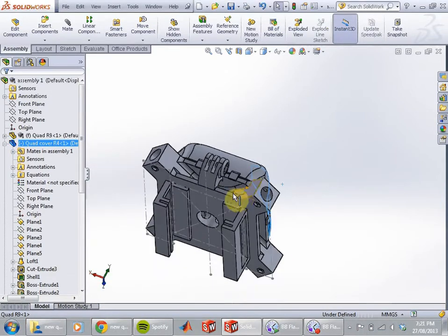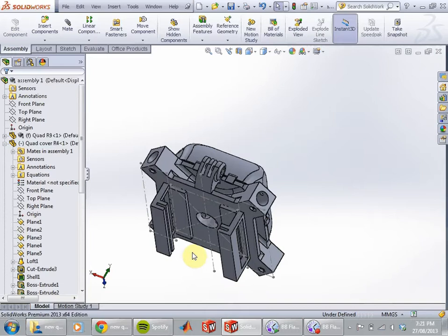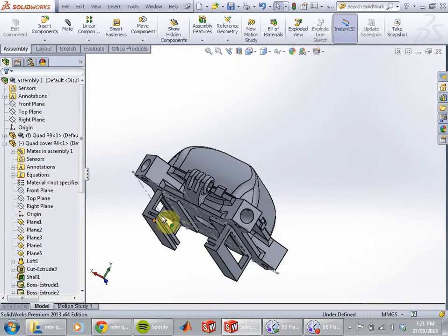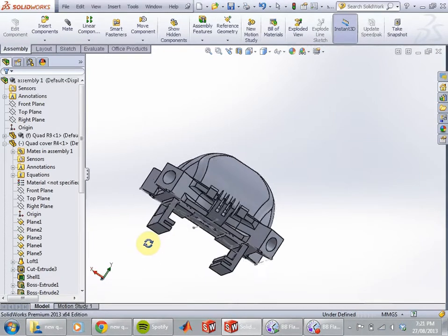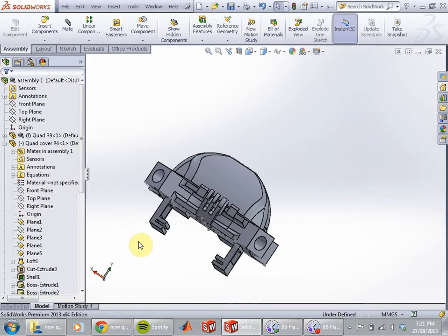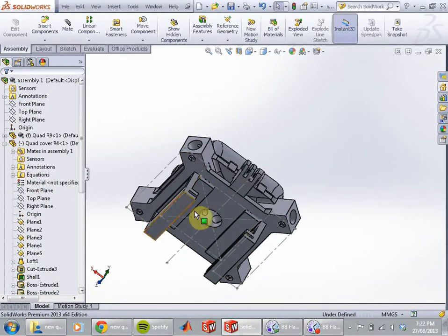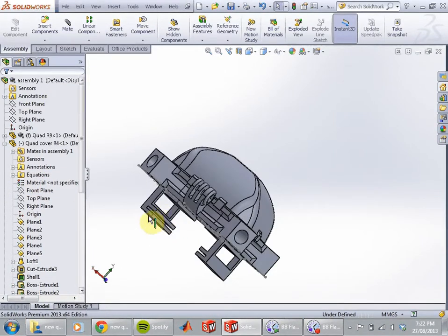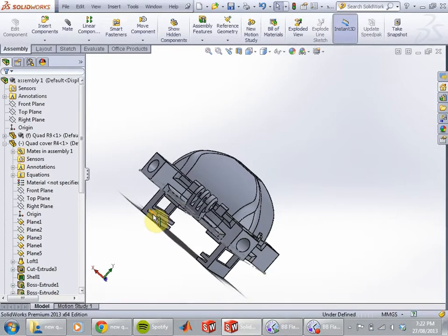The battery. We haven't put the clip in yet. Explain this. So these battery clips are going to change. This isn't final. But we need some sort of sliding system so that when the GoPro's on, it throws the balance of the quad out. So we need to be able to slide the battery back a little bit. And then when there's no GoPro on it, we need to be able to slide the battery into a neutral position. So a very primitive version of it is this, where you have the battery coming out attached to a clip, which can slide down those rails.